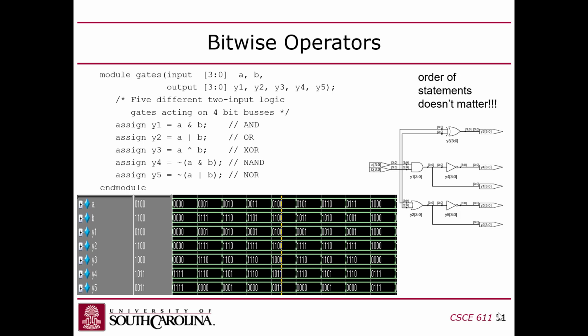Why not just put 4 there? Yes? Could you do something dumb like 8:4 and get another 4-bit signal? I think you can, but I've never seen it. That would be a perverse thing to do, and I don't know why anyone would want to, but I've never even tried it. Does it matter which way you put the numbers in? No, you can put it the other way, but I thought once that it would reverse the order of the bits. It doesn't. So you can put 0:3, and some people actually do that, but it makes no difference. So basically pick a convention and stick with it.